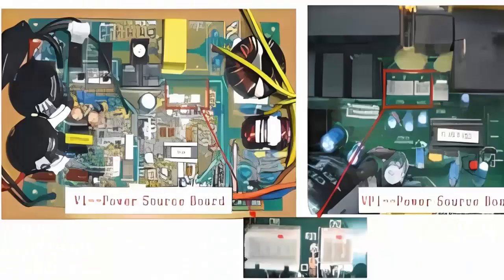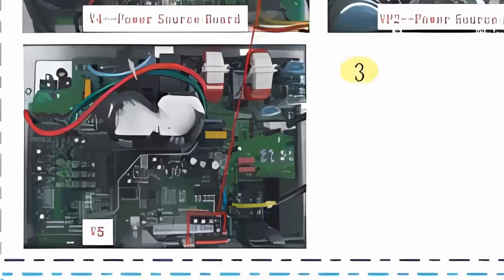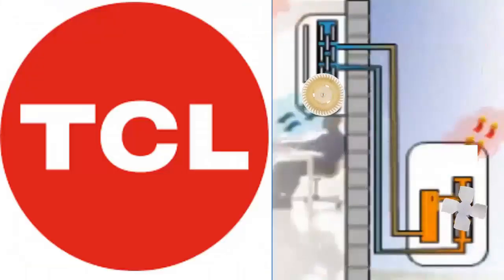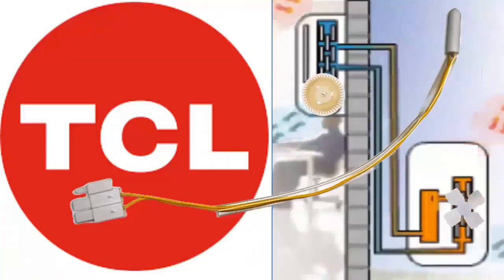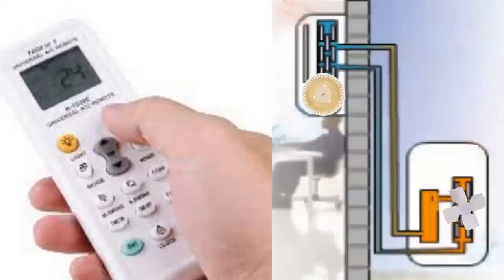3. Check the position and connection of the sensor located on the exterior unit's electronic board. Specifically, ensure that the connector for the ambient temperature sensor is properly inserted into its slot. If it's loose, reinsert it firmly. Turn on the unit and check if the E3 error reappears.